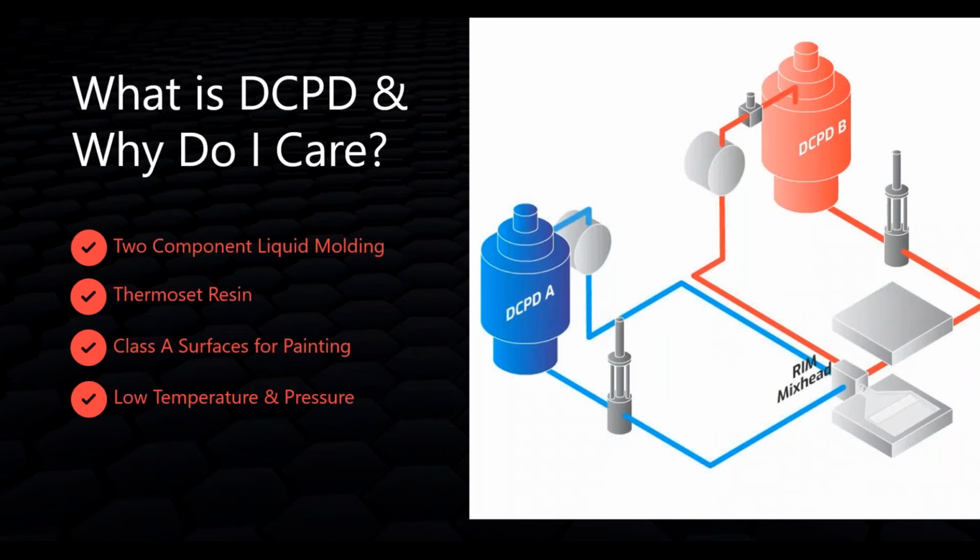Matt indicated that in some of the higher volume applications, thermoplastic injection molding, compression molding, sheet molding compound, things like that, you're a little bit more automated, and so lower material costs possibly, but the tooling cost is extremely high in those applications. So where we really fit is in that medium series volume, where customers have high physical property and high damage tolerance requirements, large parts, but maybe medium series volume. So the tooling really works quite well, and the process works well for those applications.